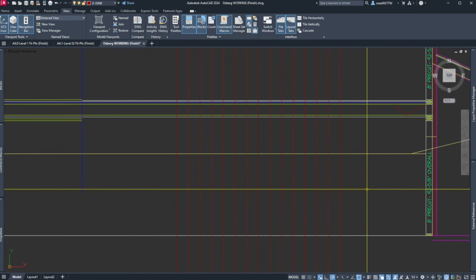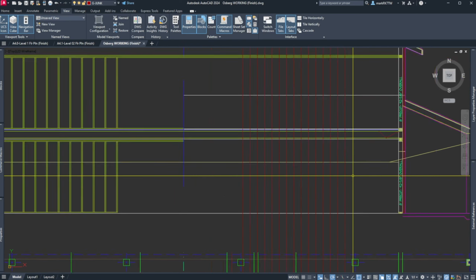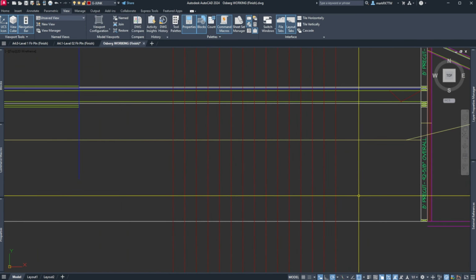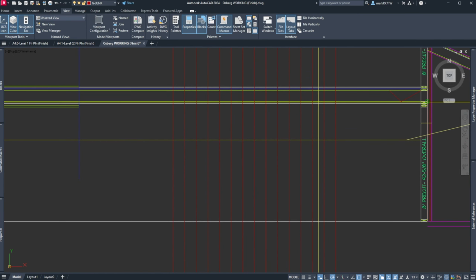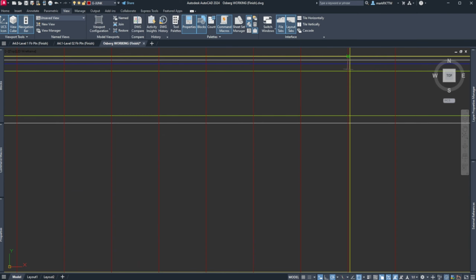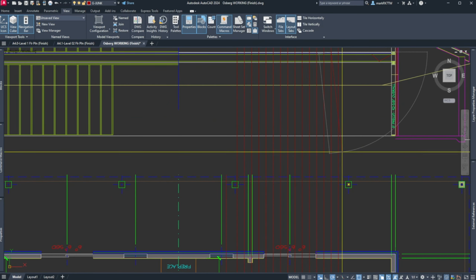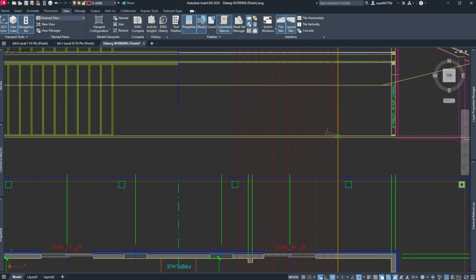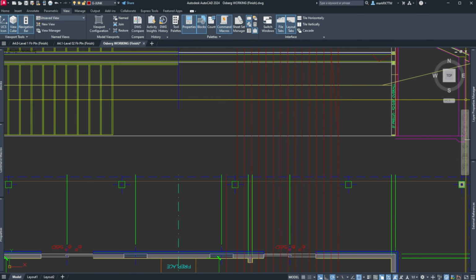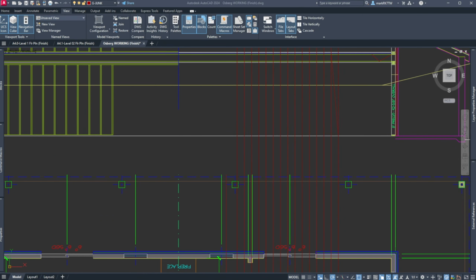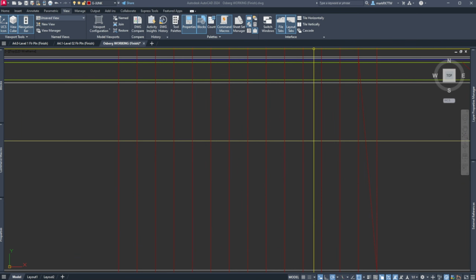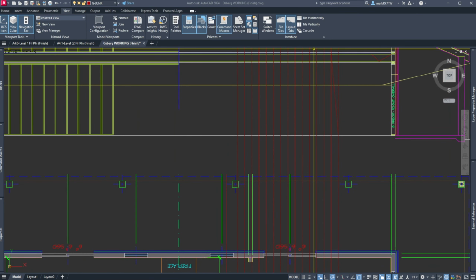And it looks like I erased my line to divide with. We'll just draw it right back in. So I'm going to go line, and I want to come from my top floor down to my slab. And then I'm going to divide that by 15, because 14 won't cut it, and 15 is a little too much. And that will give us less than 7.75, which is the max. So divide.